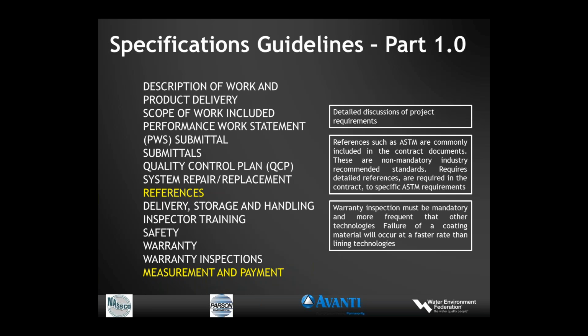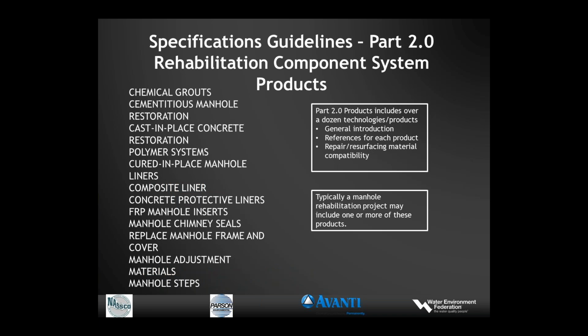during the warranty periods, not necessarily a year later, but perhaps 3 months to 6 months, and then again in a year, because coatings do have a propensity to have defects. And if those defects can be repaired very, very quickly, that will ensure the longevity of the coating. If they're not repaired, the coating may fail over time. So something very, very important to consider when selecting these materials.